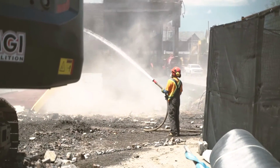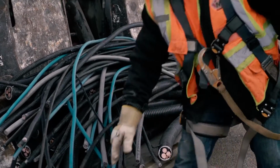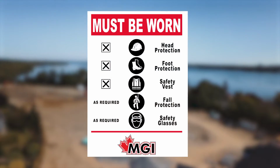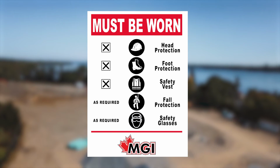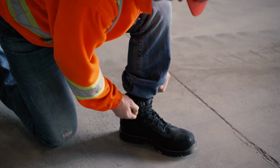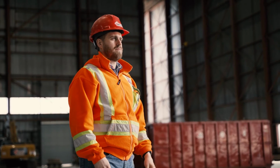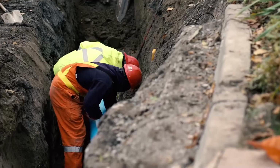All job sites require mandatory PPE to be worn for everyone's safety. As you enter a job site, you will see a sign identifying required PPE. All sites require CSA-approved work boots with 6-inch ankle support, mandatory. CSA-approved hard hat, mandatory. And high-visibility apparel. There may be additional PPE required depending on the job being completed.